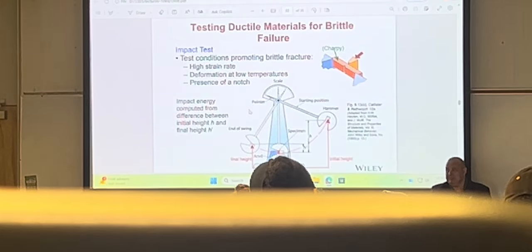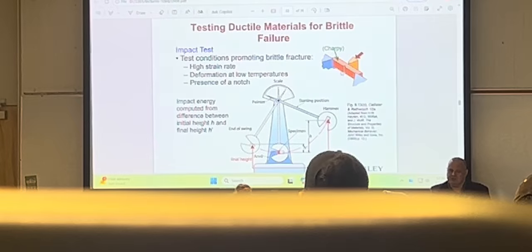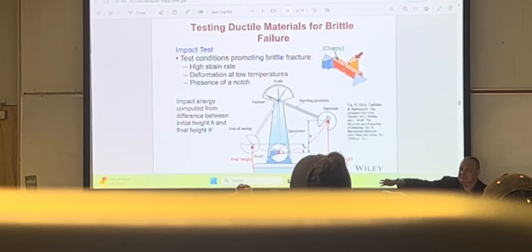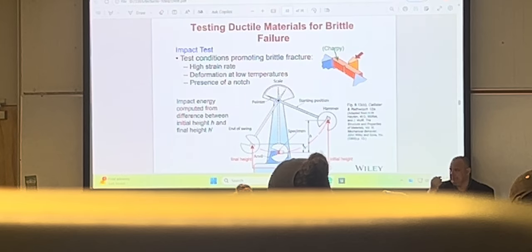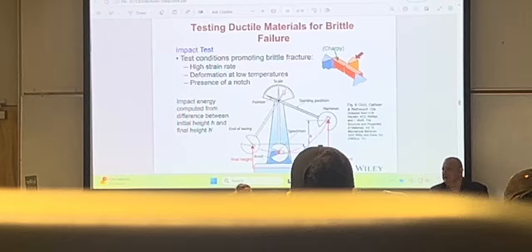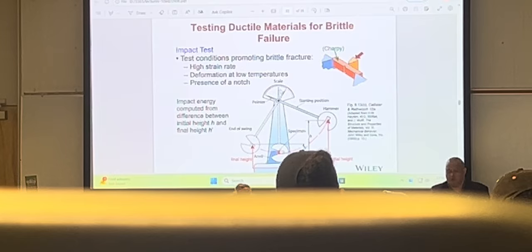What people also did not know is what's called the ductile to brittle transition. There's a very simple, crude test called the Charpy impact test. And this is the sample geometry. There's a notch and there's a hammer. You take a hammer to a certain height and you let go. And when it swings, it breaks the sample. And depending on how much energy is spent in fracture, it goes to a final height, which is measured here by a dial. It's a very crude, simple geometrical thing, but it works.